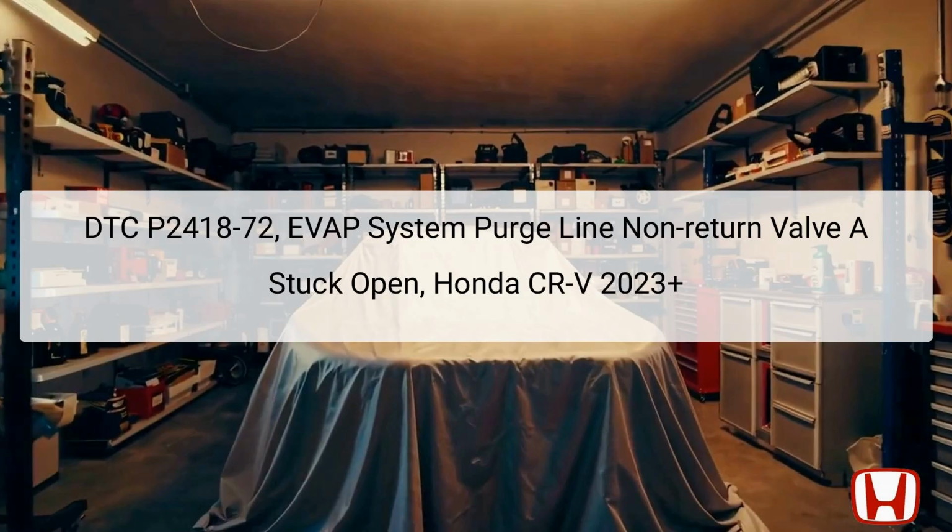The evaporative emissions control system, often abbreviated as EVAP, includes components such as the EVAP canister purge valve and non-return valves, which are vital for controlling fuel emissions. An open non-return valve can lead to excess fuel vapor being released into the environment, which is not only harmful, but also may affect engine performance.